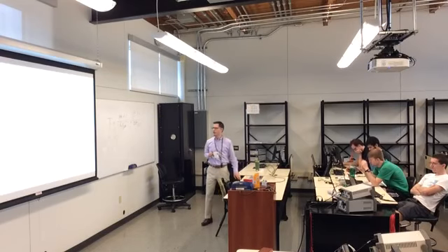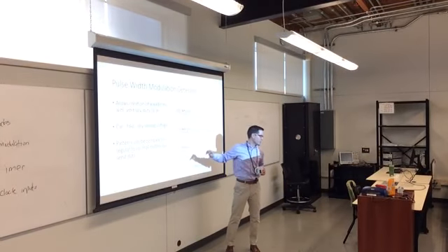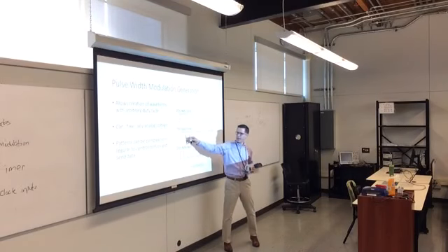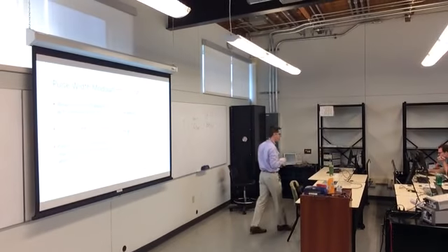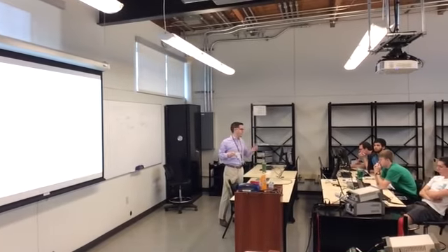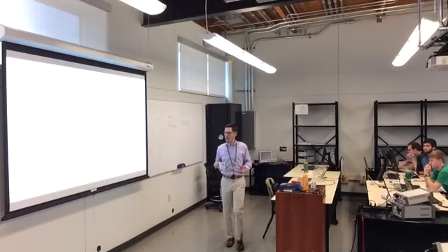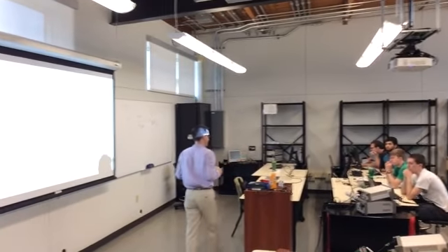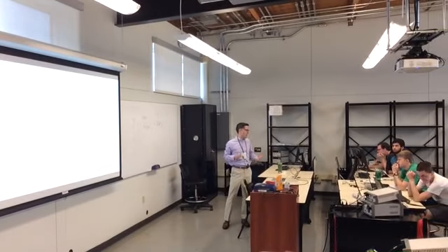As we said, a timer can create a PWM signal of any sort of duty cycle. Your regular square wave has a duty cycle of 50. This one has a duty cycle of 75. This one's got a duty cycle of 25. You don't want to do this manually. You don't want to set a timer, interrupt the processor, toggle a pin, and then set another timer, interrupt the processor, and toggle a pin, because it creates a lot of traffic on the bus that you don't need, and it makes the processor do stuff that it doesn't need to do. It's like having a human do a robot's job. Don't have a processor do a timer's job.